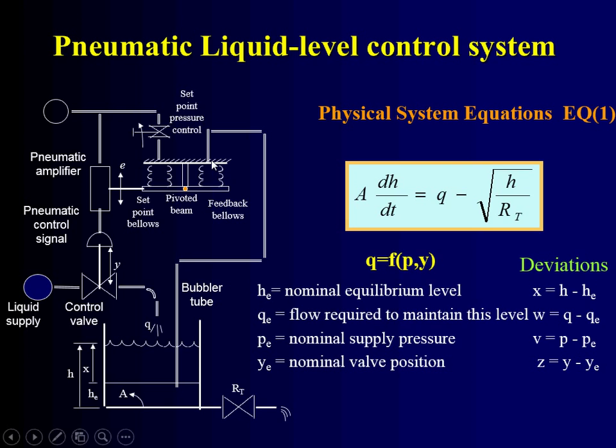If you get pressure here, you're going to switch this valve at some point, because that's what it has. The supply of water is coming here, and this would be the actuator that opens and closes this valve. So if the level goes down, this would go the other way and let the pressure flow come this way.